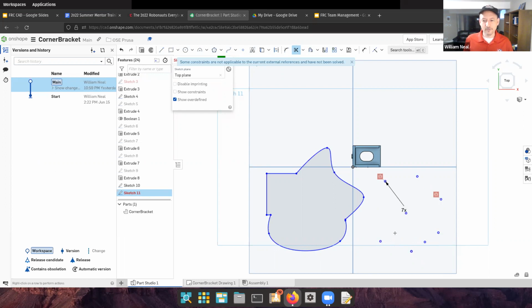There, I got rid of one set of things, but now I have my closed loop. If you look here, let's say I erase this one, it's no longer shaded. But if I go back, and you see, without clicking my mouse button, I'm just dragging here, it's highlighting it. Now I'll click my left mouse button and I may join it. There we are. If I click it and they join, then it will shade it. That indicates to me there's a closed loop. But this does not always happen.